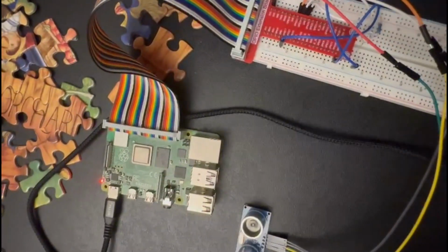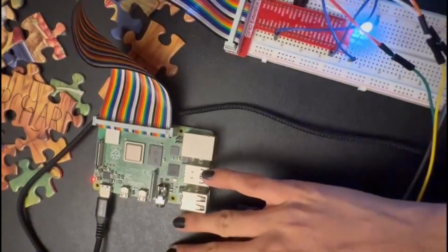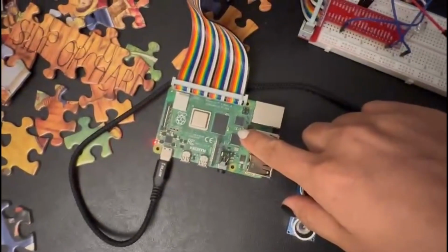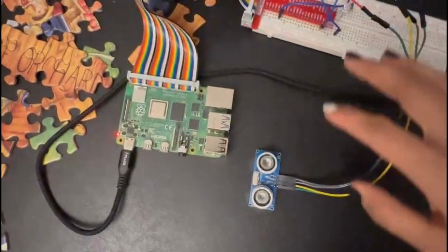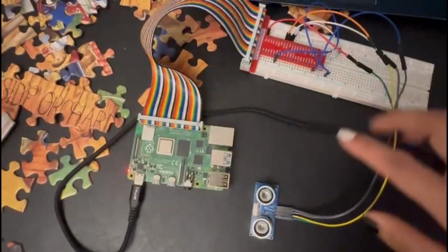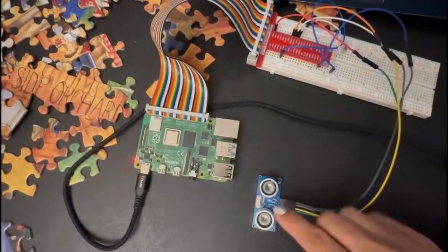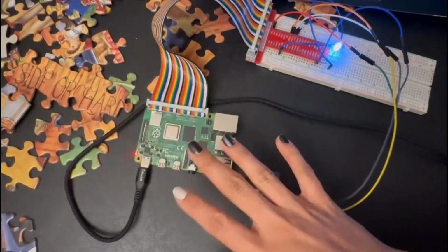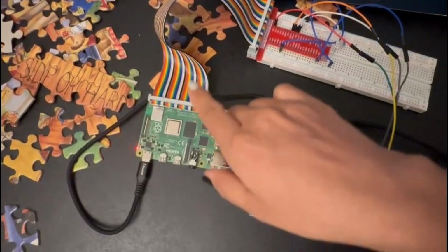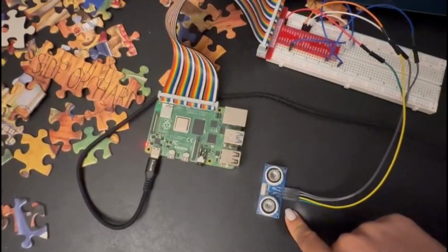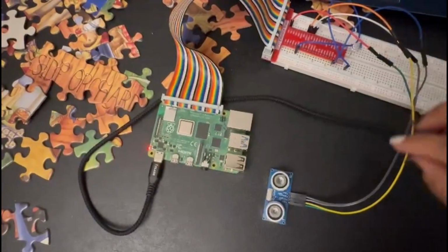This is our actuator LED that is also connected here in GPIO 17. This is our Raspberry Pi, which is the brain of this system that controls the sensor and actuator. If the ultrasonic sensor determines any obstacle near 5 cm, it sends commands to the actuator to blink. This is how sensor, actuator, and interface work.